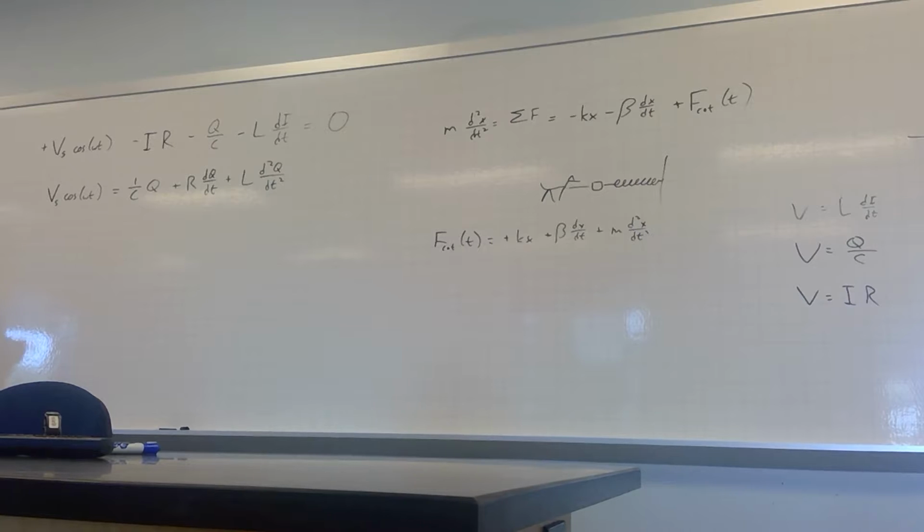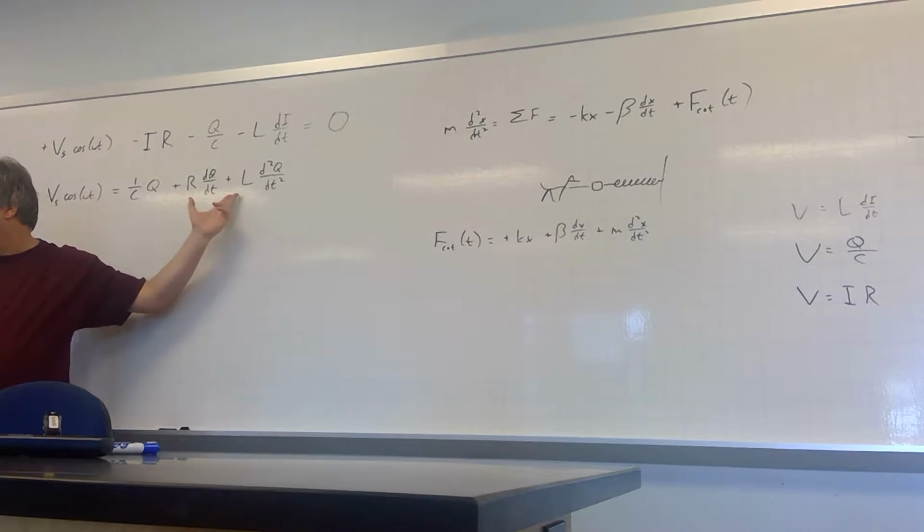Yeah. Why did you choose to put in those terms specifically? To put what in which terms? To substitute for those. Well, I wanted to have only one variable that I'm keeping track of. So I wanted either Q or I, or sometimes I use the voltage across the capacitor, but I want to put all of these things that are changing dynamically in the circuit in terms of one function.